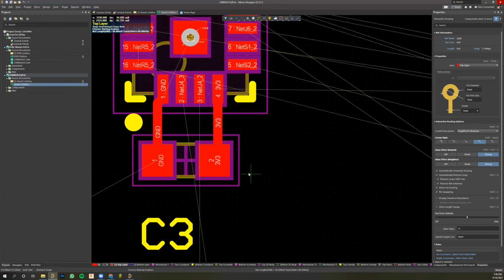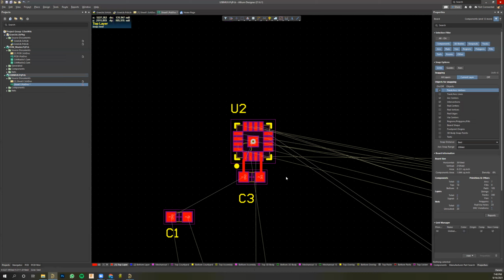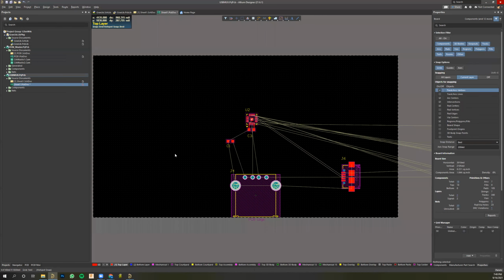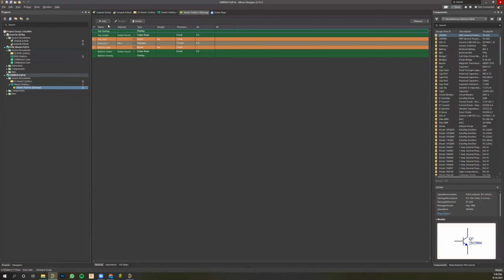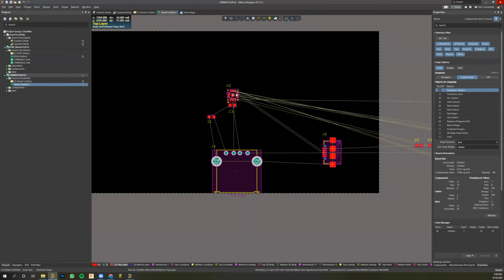And then another thing is we're going to set up, so we're going to make a 2-layer board. You could make a 4-layer board. All you'd have to do is go to design, layer stack manager, wait for it to load. Oh, there it is. And you can just add more layers here. I'm not going to, but you can. I recommend adding signal layers. You can add plane layers. They confuse me. If you learn how to use them, more power to you. I'm already an old man stuck in my ways.